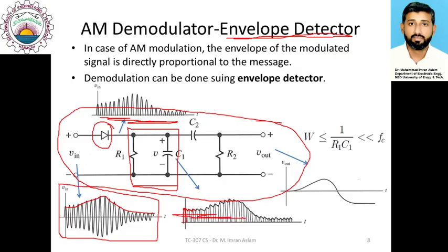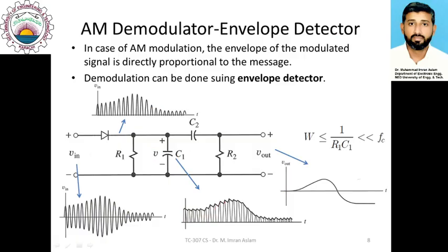So this sinusoidal variation would disappear. So at the end of the capacitor, this voltage is illustrated here. This will appear as this thick line, which actually shows the variations which you observe at the capacitor. So you can see that these variations are now following the amplitude variations of this envelope. You can see it here, but it has some DC component as well and some ripples as well.